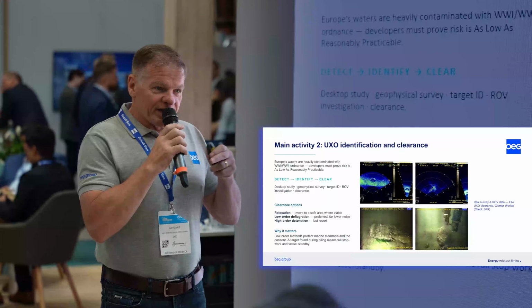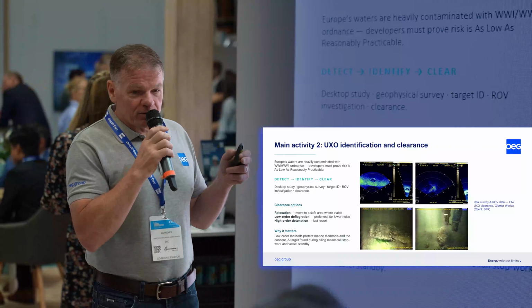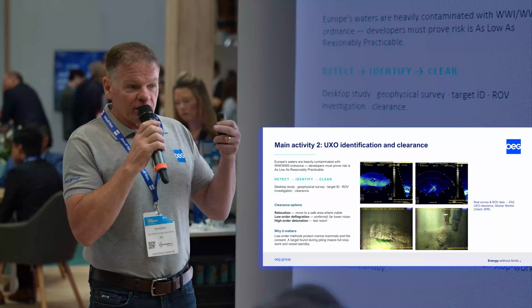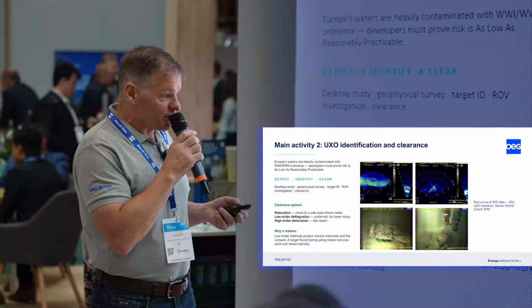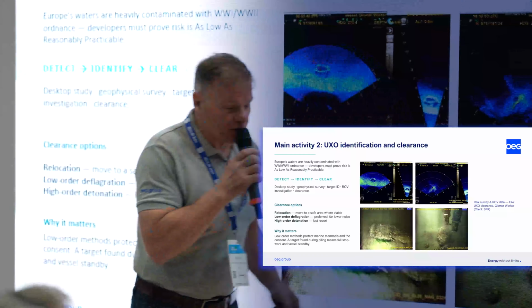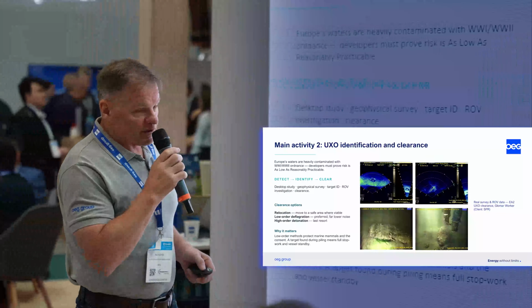We'll go in, we'll do the grid. The ROV goes backwards and forwards with a magnetometer. The magnetometer spots the target. The target, we then debury with dredging systems, which is what you can see here. This is one of the dredge systems on its manipulator arm. It will then expose the target.